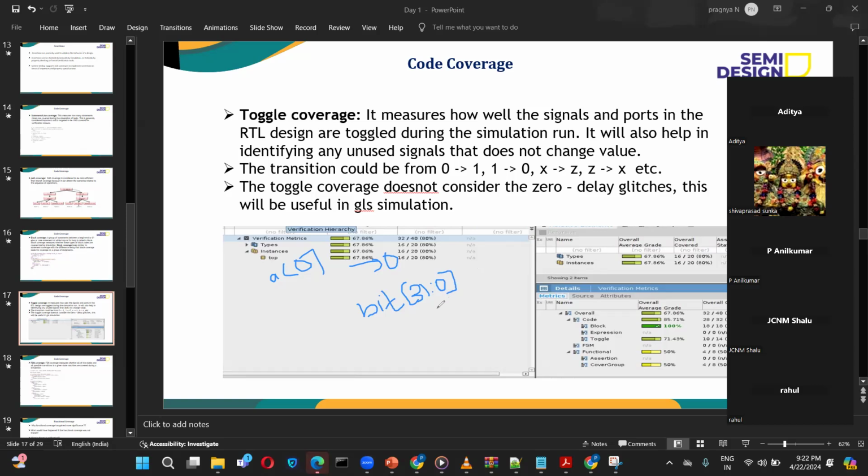In that case, we can write a reason that only the lower bits are not used. We can understand from the design why these bits are not covered. So you can directly include 16 down to 0 as lower bits if we are not using them, or if it is an aligned address, modulus 4 of 0, only those will be covered, others will not be covered.